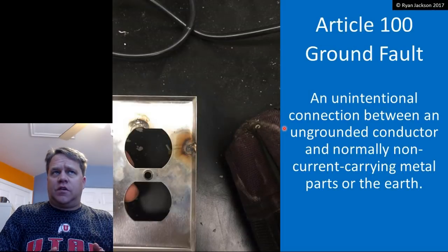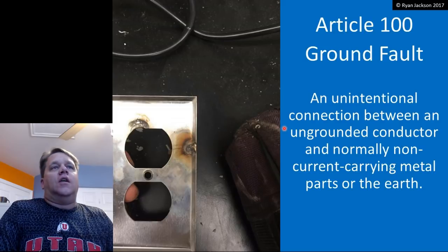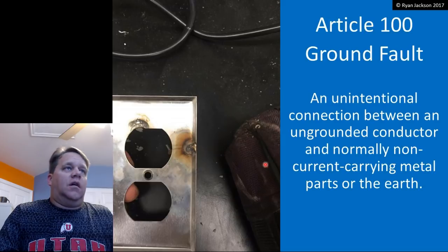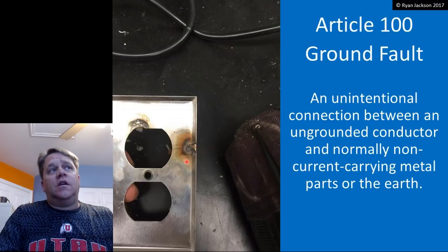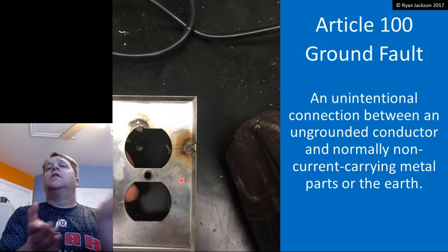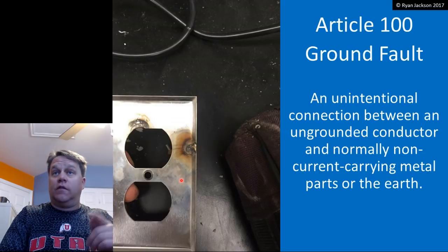The other types of overcurrent are ground faults and short circuits. Let's talk about a ground fault first. A ground fault is an unintentional connection between an ungrounded conductor and normally non-current carrying metal parts or the earth. All right, we've got a metal faceplate. We can see that the hot conductor, the ungrounded conductor, has faulted to it and created a fault. That's a ground fault, right? Taking a hot conductor, smacking it into a metal part or an equipment grounding conductor. That's a ground fault, another type of overcurrent.